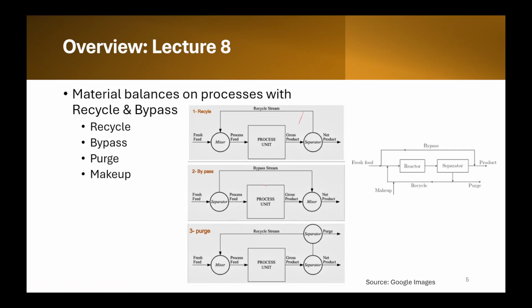So some reactant is diverted from this process system, bypassing it. Some part of the reactant is not going into this process unit. It can be used to control the process flow rate, and to control the level in the reactor as well.